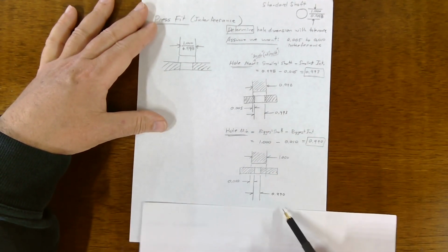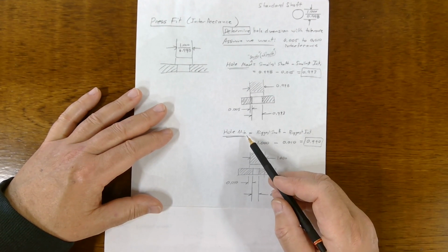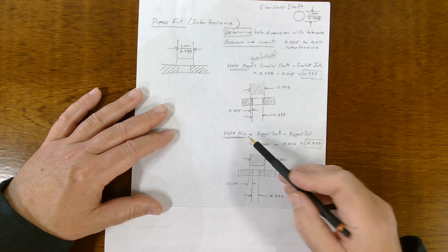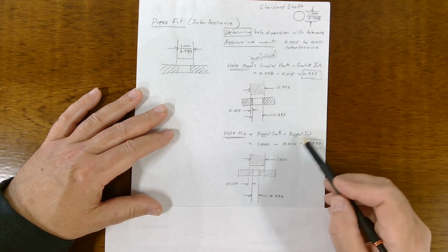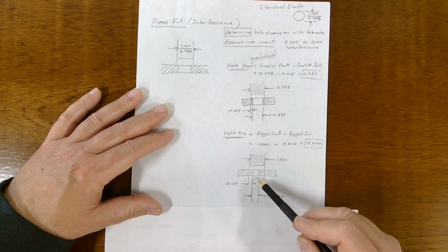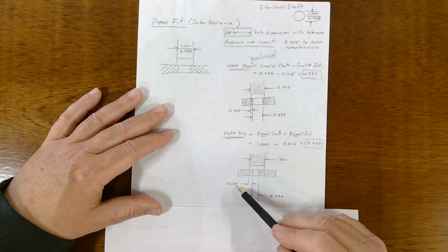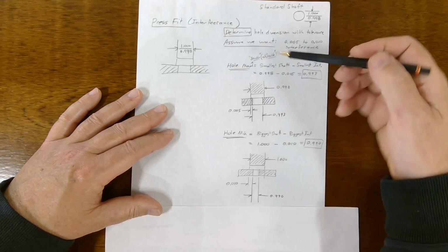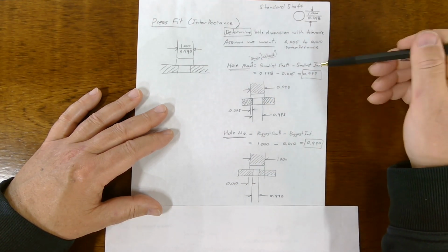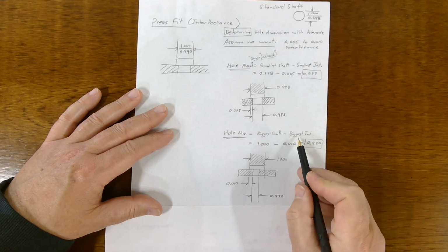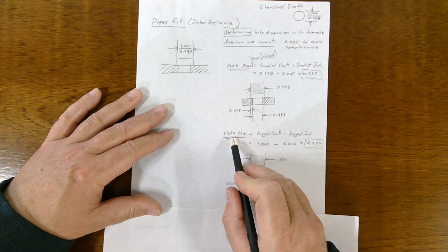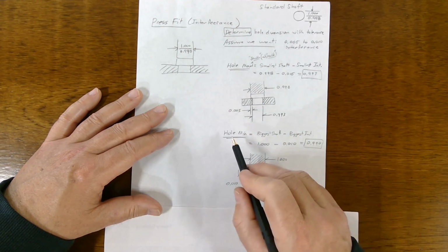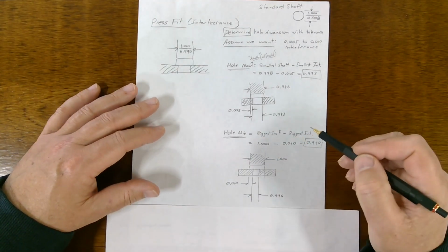Okay, and then I've got a formula here for the, I'm sorry, I mixed up max. So this is the formula for hole max. This is the formula for hole min. Just plug in the values and you get this. And you can draw it out and show, here's our interference of 10, and here's our interference of 5. Once again, use these formulas, and you might have to solve them. Like if you were asked for biggest interference, you'd move this to the other side, right? So biggest interference would be biggest shaft minus smallest hole, right? So you might have to do a little bit of algebra to find what you're using.